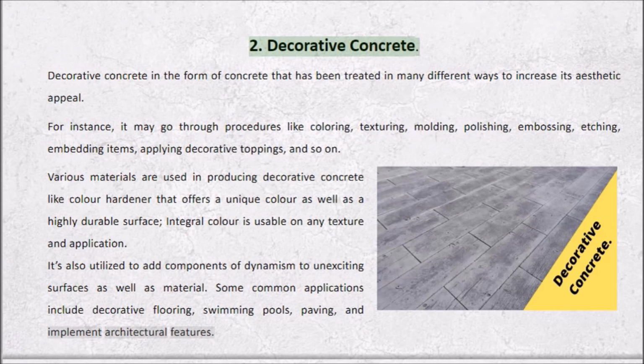2. Decorative concrete. Decorative concrete is concrete that has been treated in many different ways to increase its aesthetic appeal. For instance, it may go through procedures like coloring, texturing, molding, polishing, embossing, etching, embedding items, applying decorative toppings, and so on.